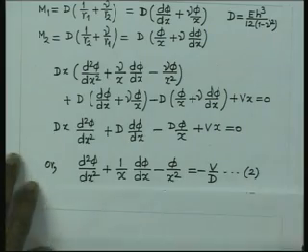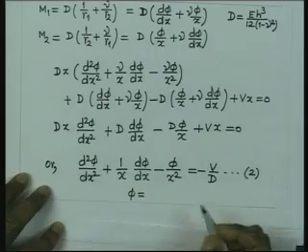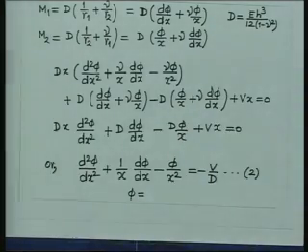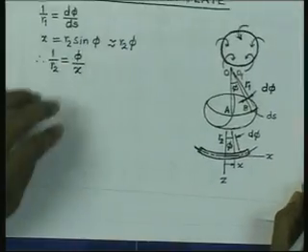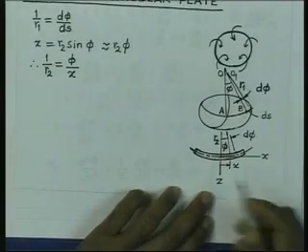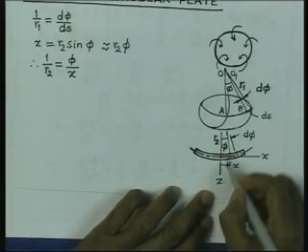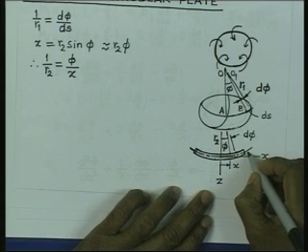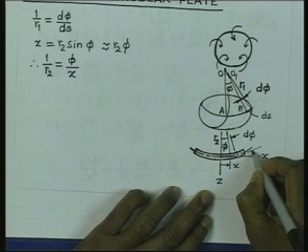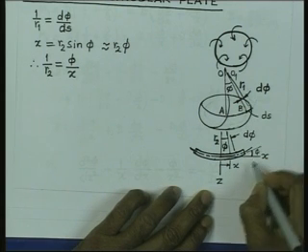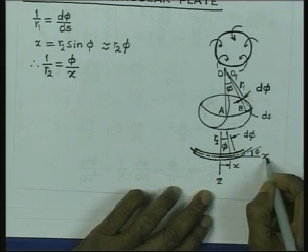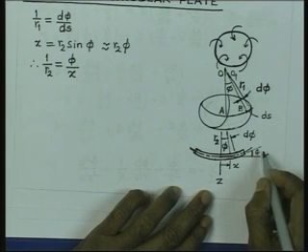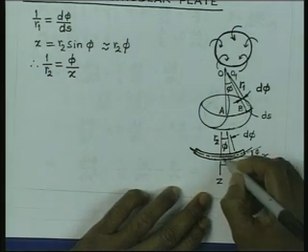So, if you now look into this, phi is nothing but, see here in the angle phi, we are considering the coordinates to be like this is x, this is z, and this is angle phi, and therefore, this is also angle phi, and in fact dw dx is going to be minus phi, because positive slope will be in this direction.